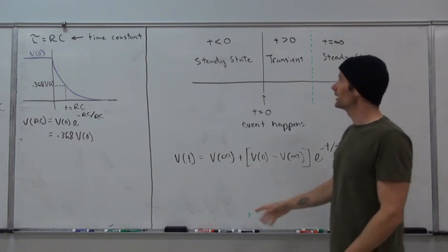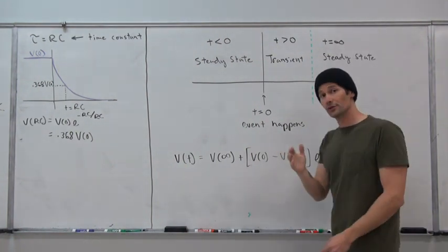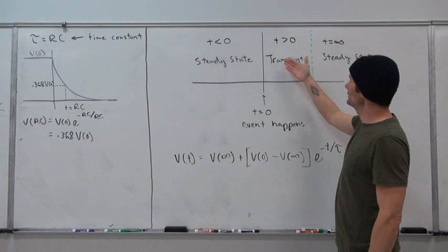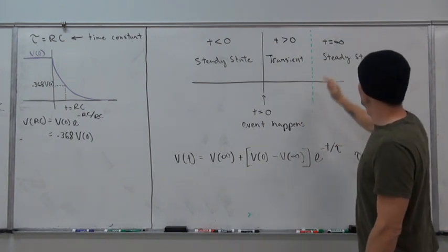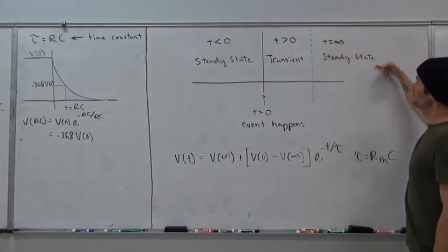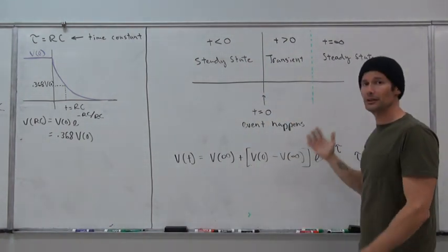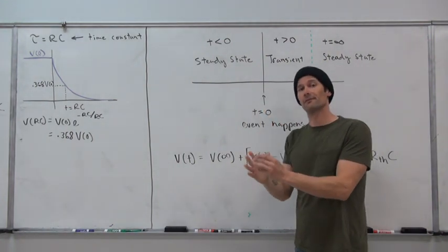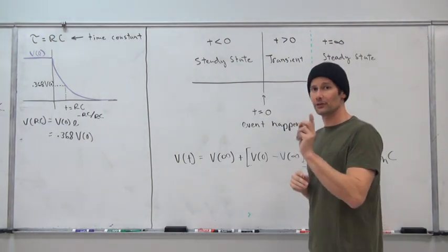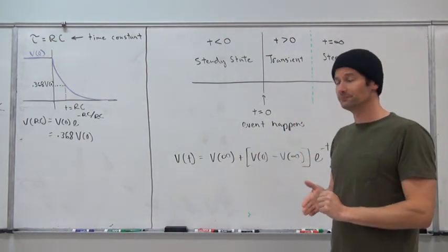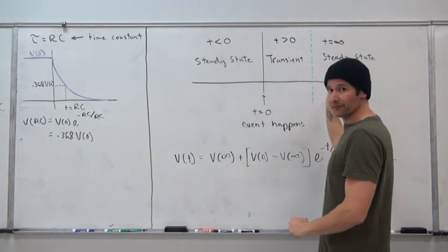So once again, t less than 0 represents the initial steady state. At t equals 0, we invoke a change. During this t greater than 0, or transient period, we see the change actually occur. And then at t equal to infinity, we have the steady state regained. What we are looking at here, guys, is what we call a total response for the voltage across the capacitor, and the solution after solving the differential equation is complete and models every bit of this.